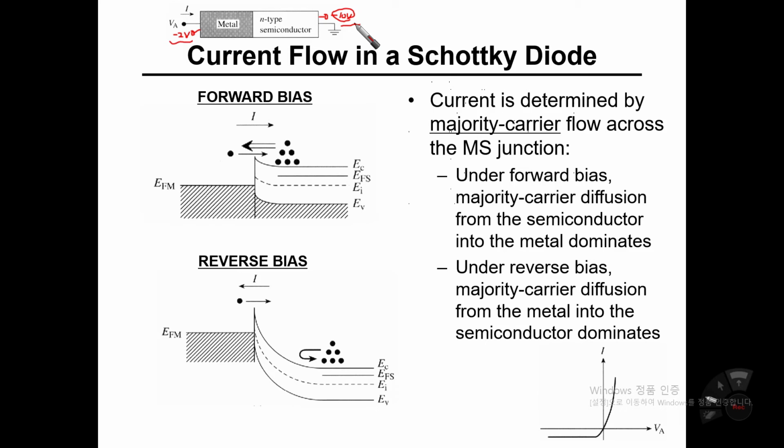That is totally wrong. Keep in mind how much voltage difference has been applied. As long as a higher voltage is applied onto the metal side, we can say that the MS contact is forward biased. So please remember this, and don't be confused into thinking positive bias is always equal to forward bias. That is not always true.